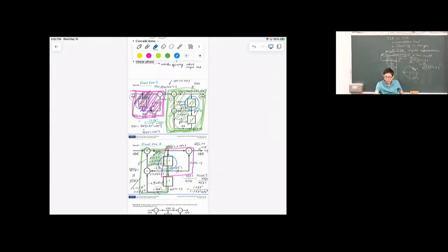Now the direct form 2 has the beauty of placing the delay line in the middle because the two subsystems share the delay line. That's a good thinking. That's good design. I personally really like it, from the first time I saw this. This is possible because of the commutativity of LTI systems (可交换性). So we have direct form number 1 and direct form number 2.